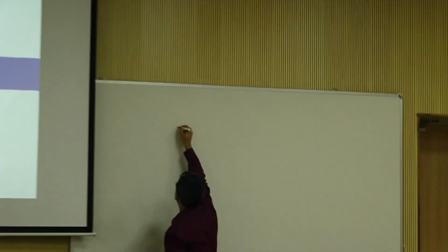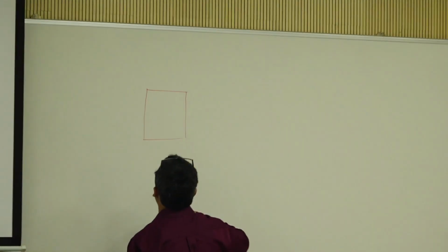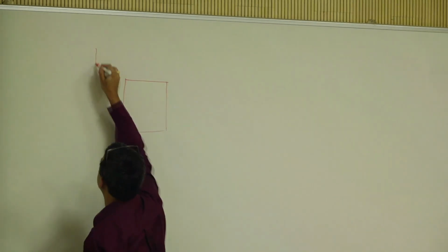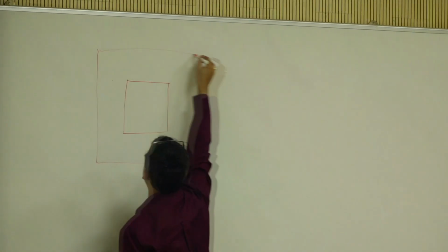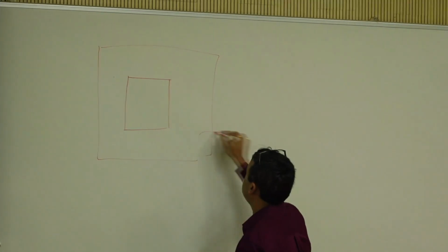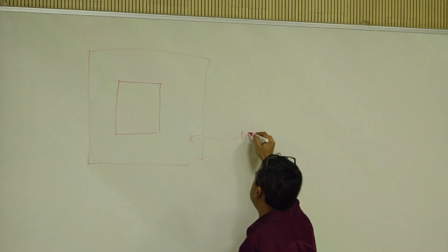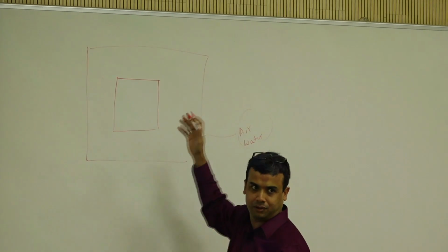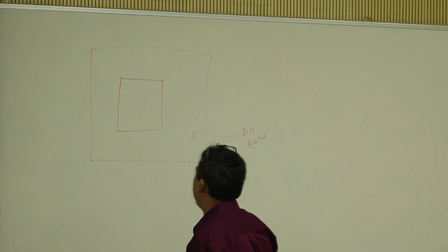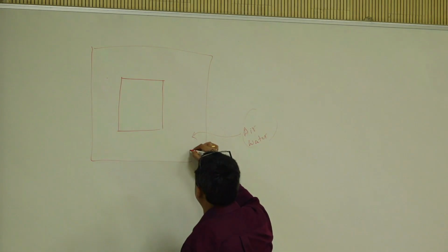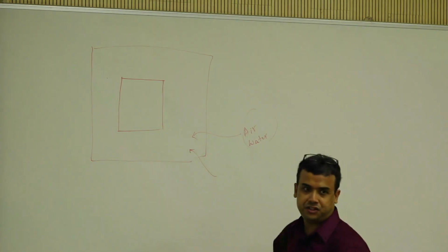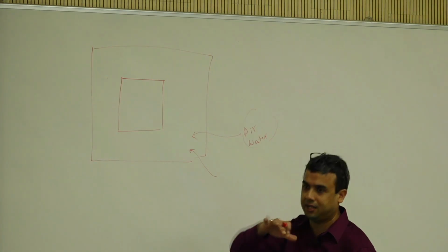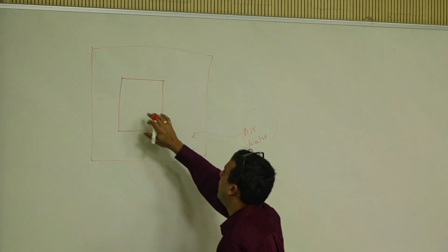So we're talking about cylindrical triaxial, and you know why it is cylindrical, we talked about it. So we have a chamber. Inside the chamber we have some kind of a confining fluid. When you apply some kind of a confining pressure to this chamber, it's Pascal's law, it is normal in all directions, it is hydrostatic, it is equal in all directions. So what happens is